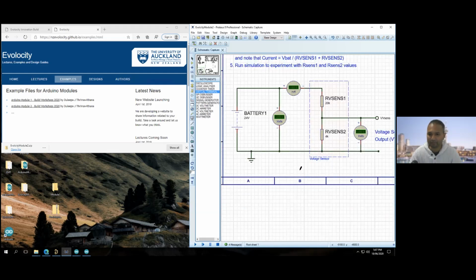So you use Proteus to find the golden ratio to get between 0 and 5, then you go out and buy those resistors? Yeah. But also keep in mind that people don't make resistors for every single value there is, because then there would be billions, millions of resistors, right? They make them in very discrete numbers. So you might have to compromise between what you think is the best and what you can buy.